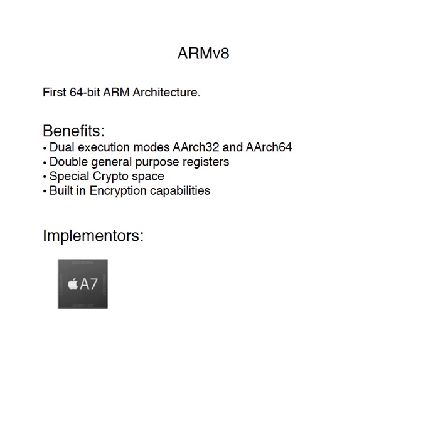That's a key thing. Apple A7 uses that space to store the Touch ID information, that is the fingerprint information which they take from your device. They store it in this memory, which is on the chip, which means nothing else can access this data apart from this single processor, and it is built-in encrypted. So these architectures have built-in encryption capabilities to do all these things. That's an incredible thing for a processor like the A7. So that's about ARMv8.